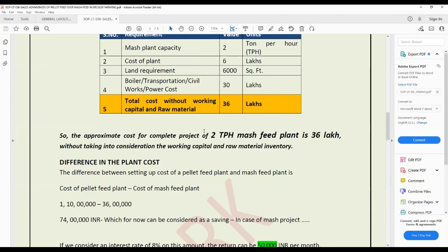And what is the power consumption you need for that? So the power required for the machinery is around 160 horsepower. In kilowatts, it is around 125 kilowatts. I think that is achievable in my case. Actually, we have a lot of power issues. That is why I cannot go for a pellet mill, because I have a maximum of around 75 kilowatts capacity in my area. More than that is not available in my area. That is one of the constraints for me.